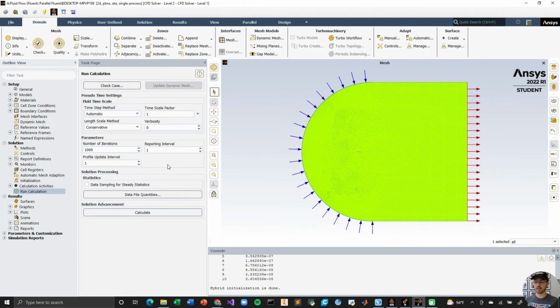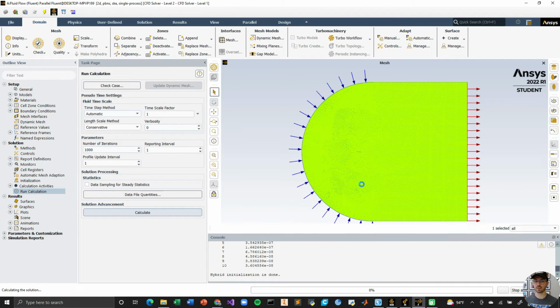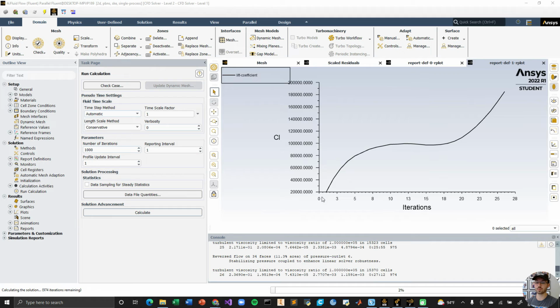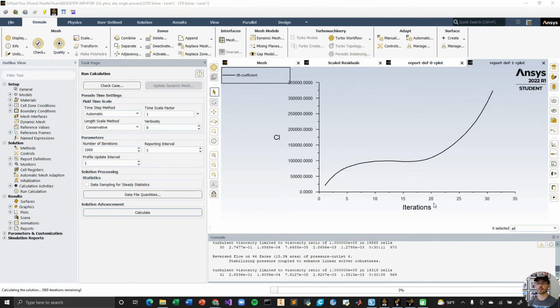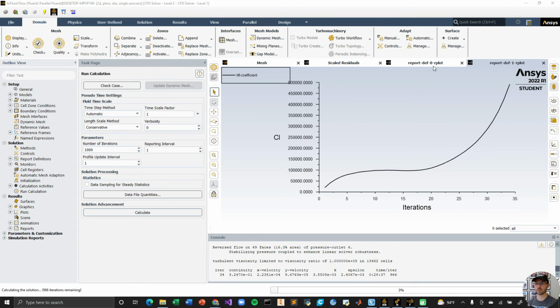But more importantly, it's going to be a more reliable calculation because it'll run through the scenario time after time after time, so that our data is going to come through and be statistically significant. Now that we have a decent number of iterations for our calculation, all we have to do is click calculate and sit back and wait for it to load. And this is actually really cool. ANSYS will show you in real time the graphs that we defined earlier, developing and generating points. So you can see that for the lift coefficient as well as for the drag coefficient.